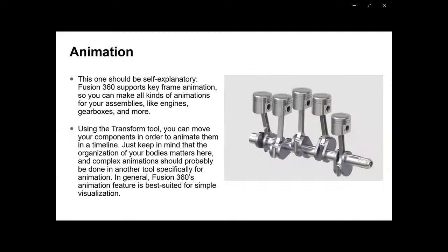So similarly, we have animation. Animation is where you can apply the joints and see the actual animation of your machine. You can link the different motions together by using the motion link. Suppose you have two different motions where there is no link between those two joints. That option is also available by using motion link and motion studies. We can connect multiple joints together and have the full-fledged animation of our component. So that is the animation part.